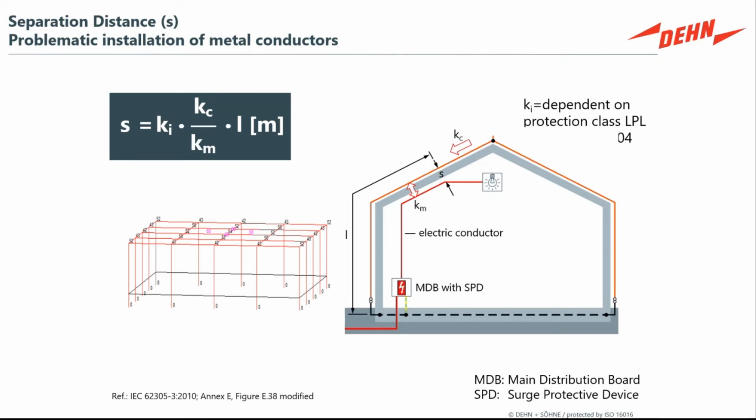And in our IEC methods, we have a calculation that does depend on the risk and the lightning current, but it also depends on the height and the types of materials that you're subjected to. So with these types of tools, which are very similar to bonding distance calculations found in NFPA 780, we can determine if these apparatus are sufficiently spaced apart.